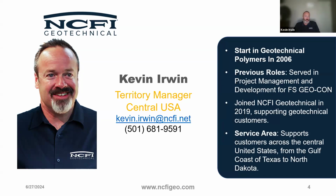On the density issue, just real quick, I know with my business, we lifted 72 tons with a 2.5 pound foam. So are you putting all the rods down at once or drilling through the foam to drive the next rod? All down at once. Don't like to have to try and get back through that foam. I've got video of somebody jackhammering back through some of our NCFI 24003, and the only way they could get through it was with a jackhammer.